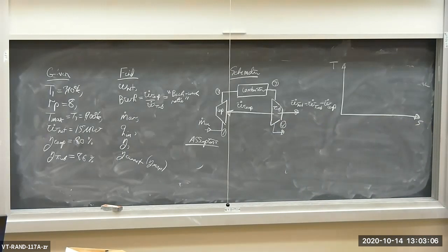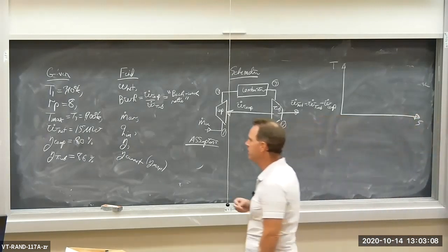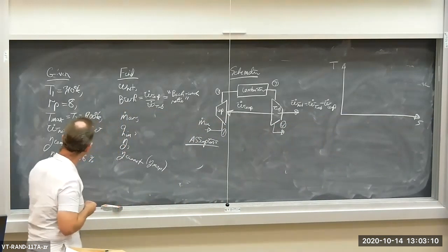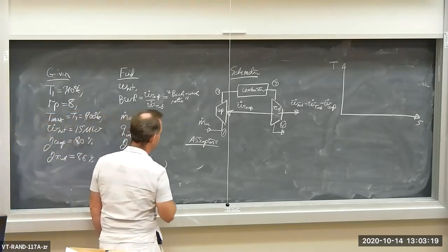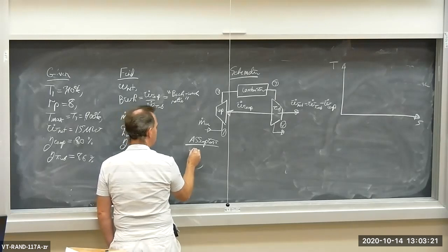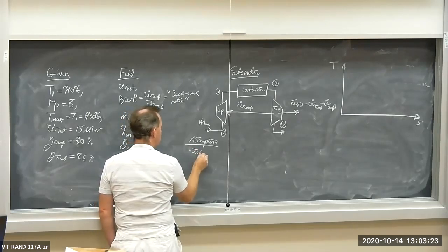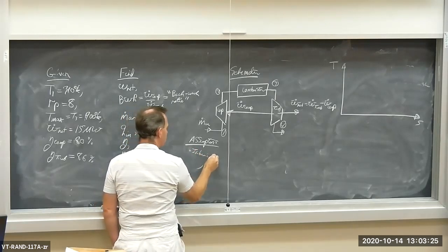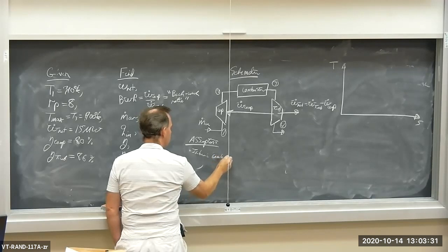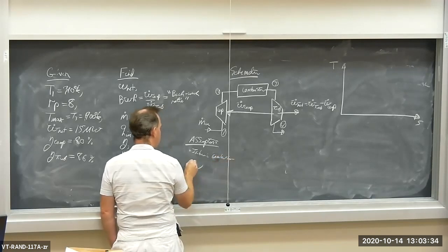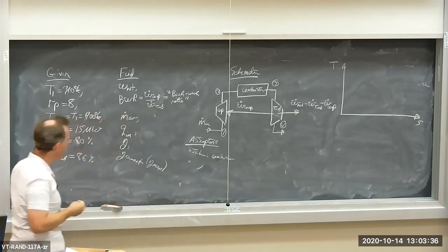Okay? Now let's make a few assumptions here. I don't see any actual explicit statement, but let's assume that there's no pressure drop across the combustor. I don't see that there's a delta P across the combustor in the givens. So I'm going to assume an isobaric combustor. I also don't see it stated, but I'm going to assume it.